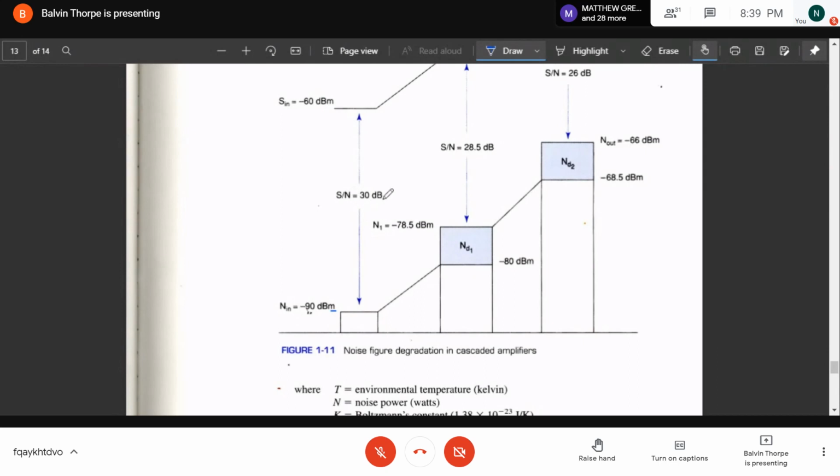So the signal to noise ratio between the two signals would be 30 dB and not 30 dBm, because there's no need to measure with reference the difference, because we already stated that the two signals were at the same reference point by referring them to 1 milliwatt, right?